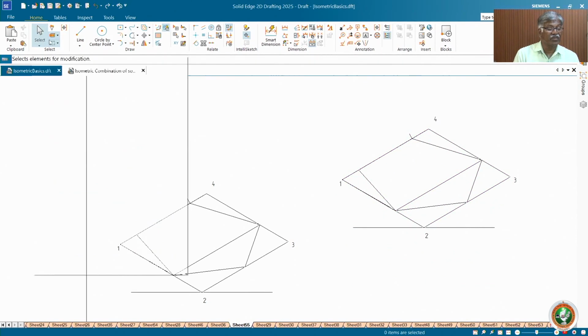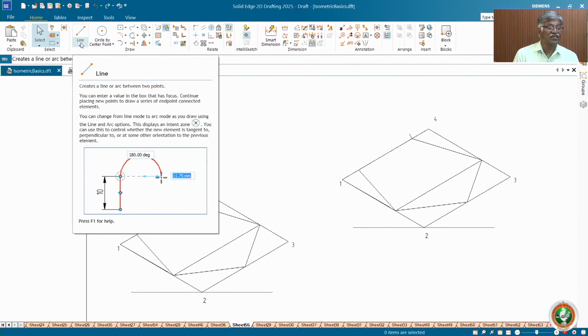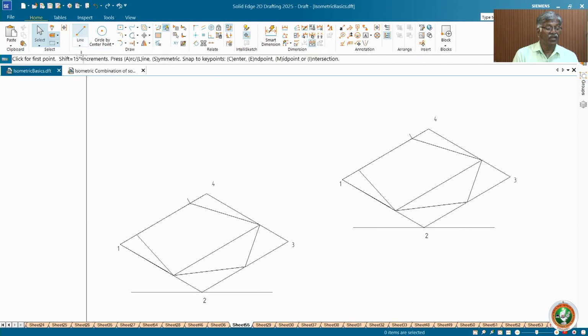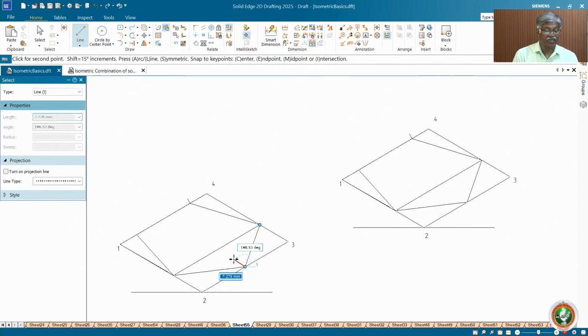Now for the frustum it is the same procedure as the pyramid, because it's a frustum of a pyramid. Now you identify the center. First you select two corners and join them with the midpoint of the opposite side. Then you will get this.